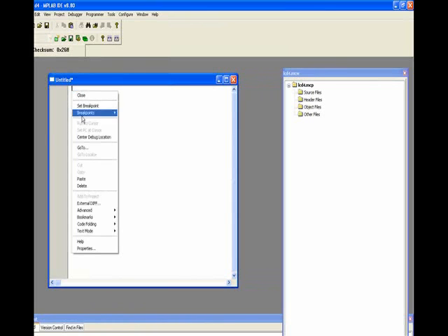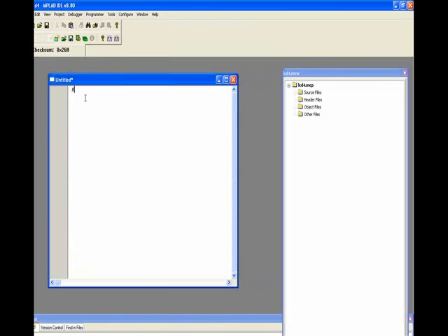Okay, now I'm going to paste this sign there. For some reason I can't find it on my keyboard, I think I've changed my keyboard layout, so I've just pasted it there. Now I have to include the device, so open brackets 16F887, then close brackets. Okay, next line, I'm going to set the fuses.